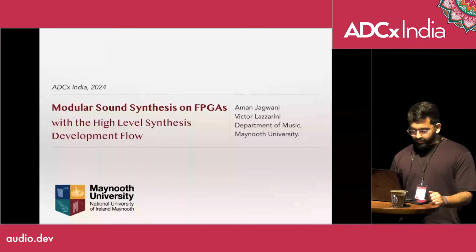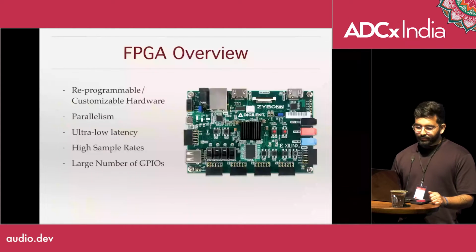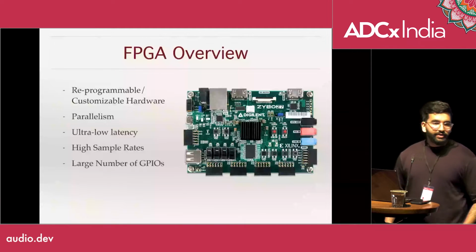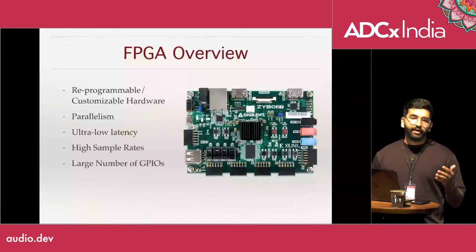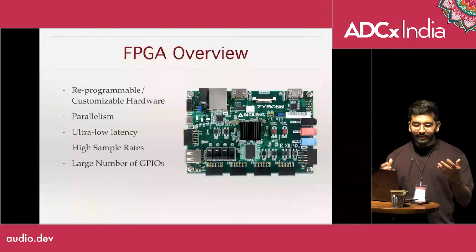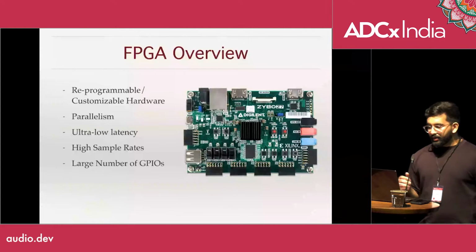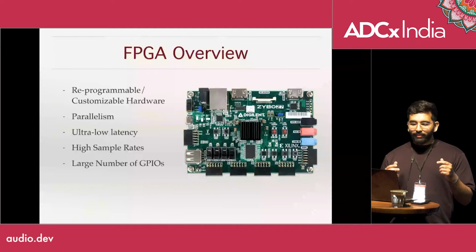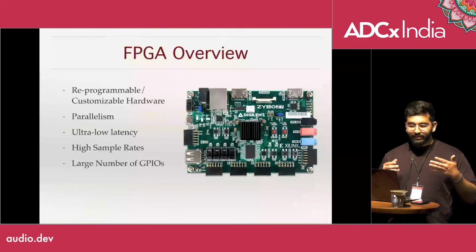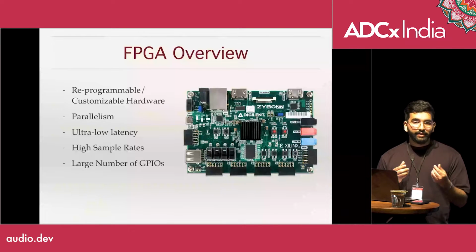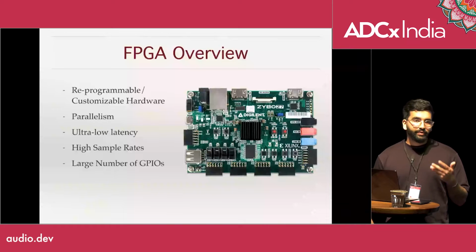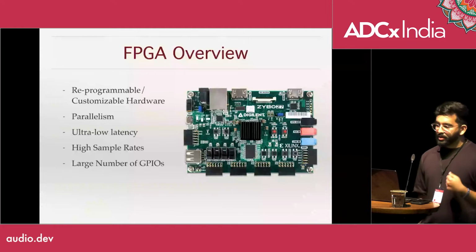Before we start, I'm just going to give an introduction to FPGAs. FPGAs, or field programmable gate arrays, are integrated circuits. They're like chips, like the microcontrollers or CPUs on our phones and all our devices. The difference is that they are reprogrammable and customizable. You are actually able to change the electronic circuits, the logic units within the chip. It's mostly done with specialized hardware description languages like VHDL and Verilog.